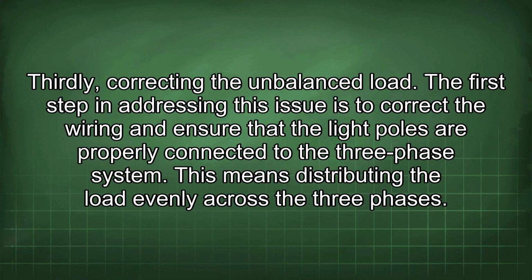Thirdly, correcting the unbalanced load. The first step in addressing this issue is to correct the wiring and ensure that the light poles are properly connected to the three-phase system. This means distributing the load evenly across the three phases.